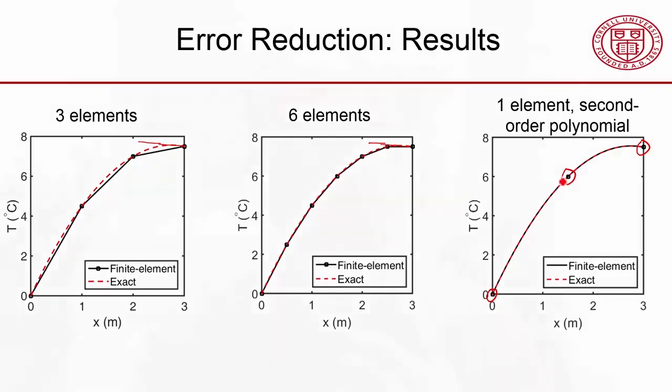interpolation. In general, the second order interpolation is very effective, and here it's probably not as dramatic as over here, but it's very effective. And when we go into Ansys, we will see that in almost all cases the solver puts in the mid-side nodes and uses a second order polynomial rather than a first order polynomial.